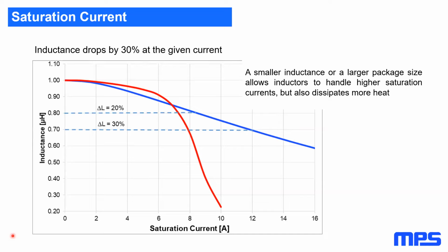Great. Next up, for the inductor measurement comparisons, did you actually measure the actual parameters like RDC, or was it based on the specification? We're using efficiency, comparing the whole device with the input voltage, output voltage and the currents, and we are driving by the frequency at several points from 0 to 3.5 amperes in this case. Overall, we're measuring certain points of efficiency when loading, when putting some currents, and those are the results. This is not really based on RDC alone. It's based on RDC, or copper losses, and core material losses. It's the complete losses in general.